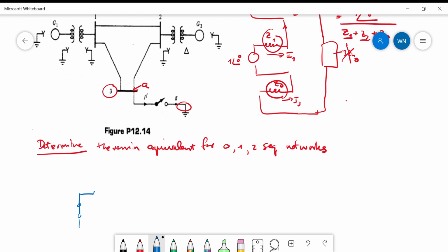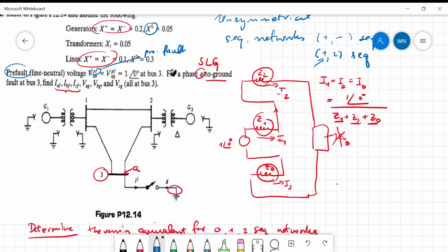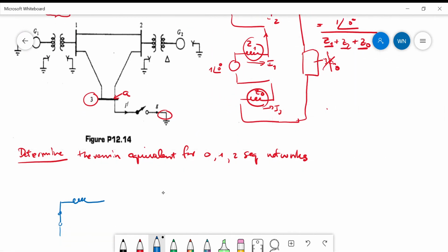And you have the generator G1 in this case, and the parameters are given, right? It was given as J0.2, if I'm not mistaken, and it's connected through the transformer. So in this case, the connection of the three-phase transformer does matter when you consider just positive sequence. Zero sequence. Okay, you remember that the delta connection for the three-phase transformer will play the role just in the zero sequence network. So you have to take a precaution with that zero sequence.